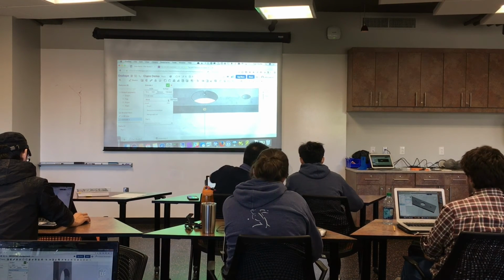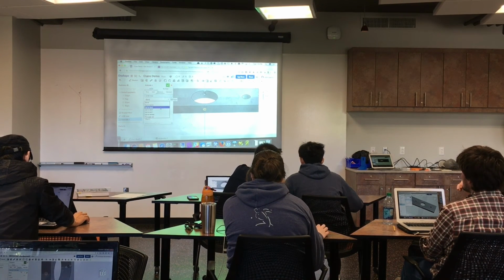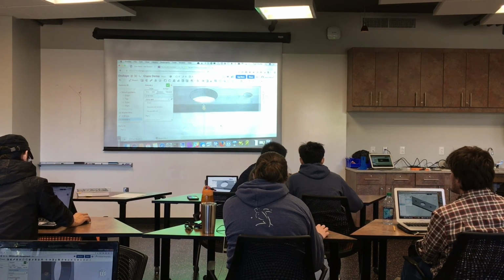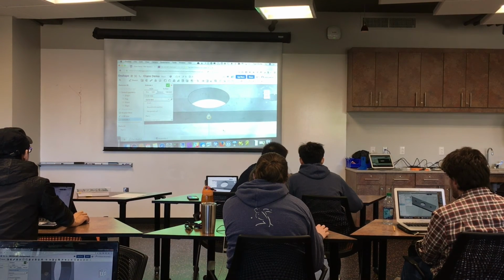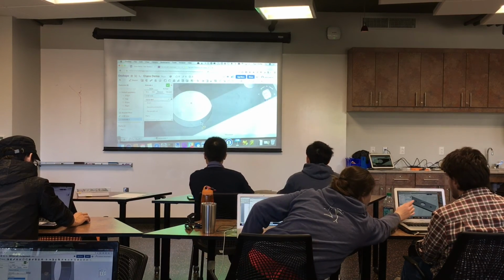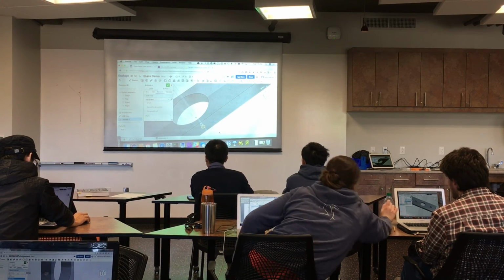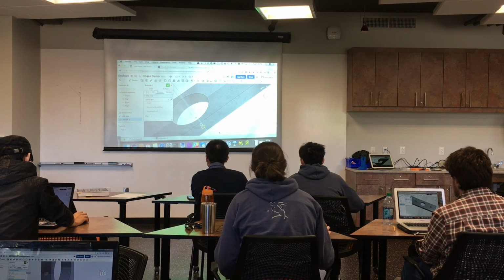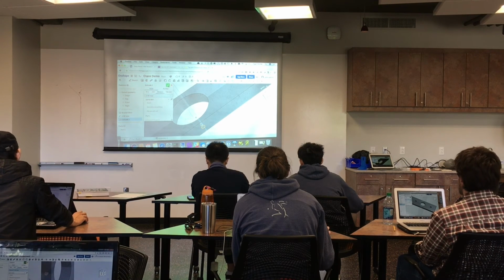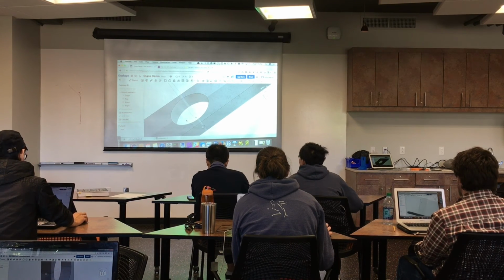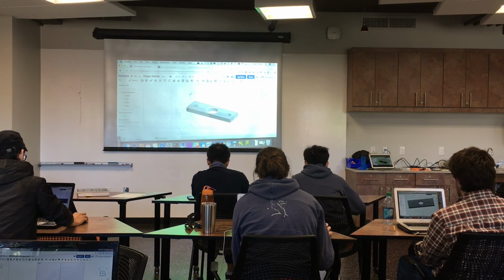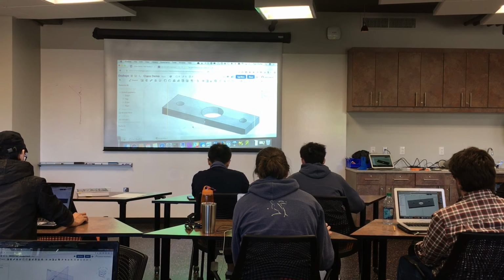So in this menu that says end type, say up to next, which means it's going to go up to the next face. So now, if you look, it's gone through there, but nowhere else. So it goes through the next face as well. Right, yeah. Okay. And then you click the green check mark. And now you have a beautiful, almost finished part here.